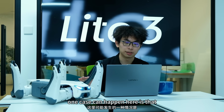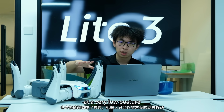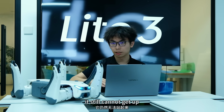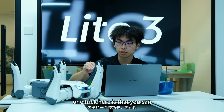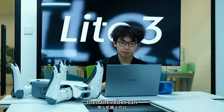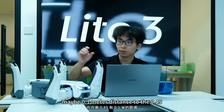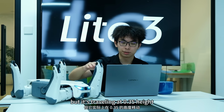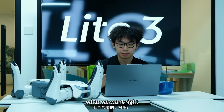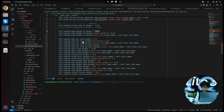One case that can happen here is that maybe you tune the parameters a little bit and the robot can only traverse at a very low posture. And even though you increase the weight a lot, it still cannot get up. One trick here is that you can change the desired height to be higher than the actual height, like 0.45 here. Then the robot still has maybe 0.1 meter distance to the 0.45, but it's traveling at a 0.35 height, and this is what we want, right? Sometimes this can help with a corrupted set of reward parameters, okay?